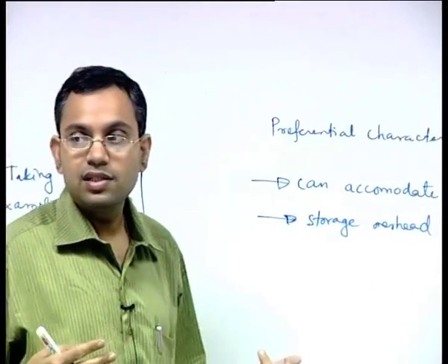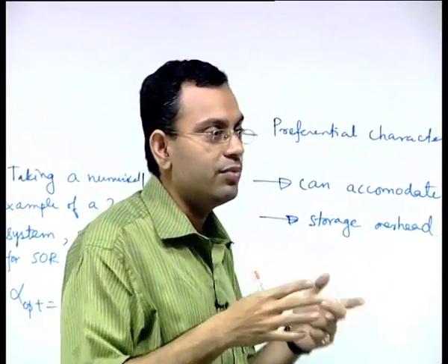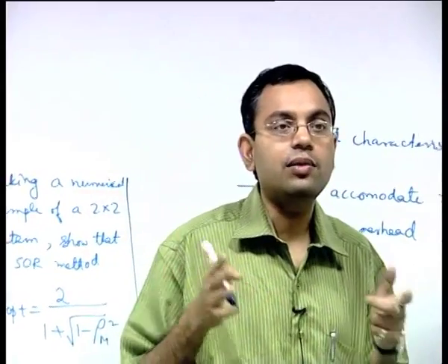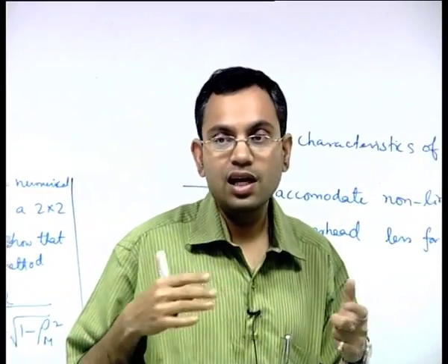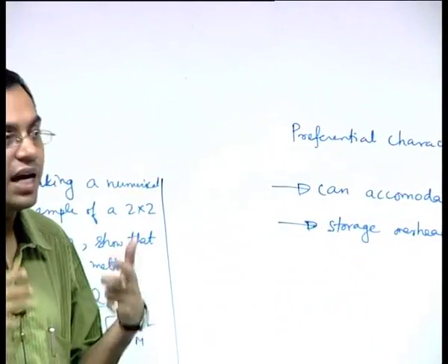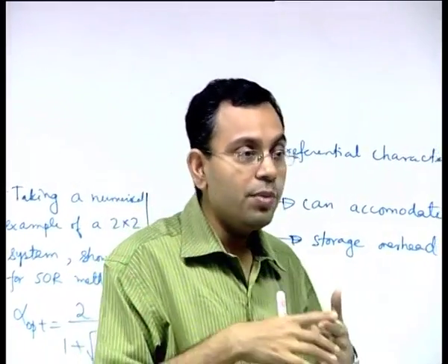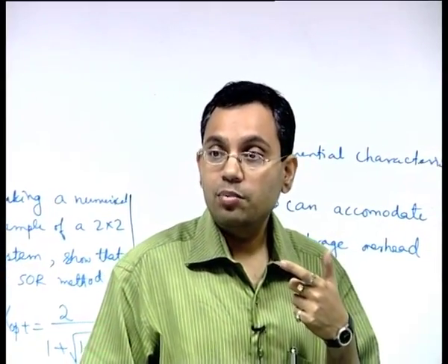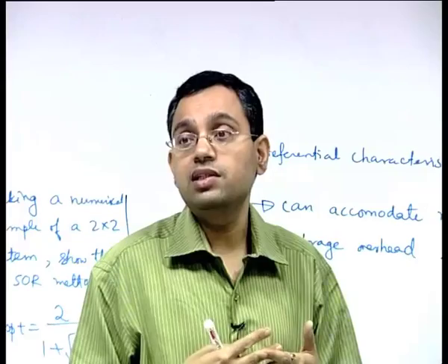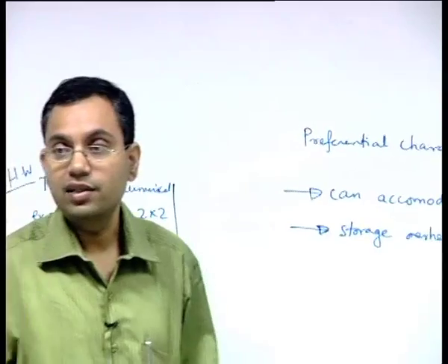So if you use a refined mesh, and many times we use a refined mesh to get a more accurate solution, that is the natural tendency, but at that cost what we sacrifice is that now we have reduced rate of convergence. So we will be getting more accuracy hopefully, but with a much reduced rate of convergence which perhaps we are not able to afford.